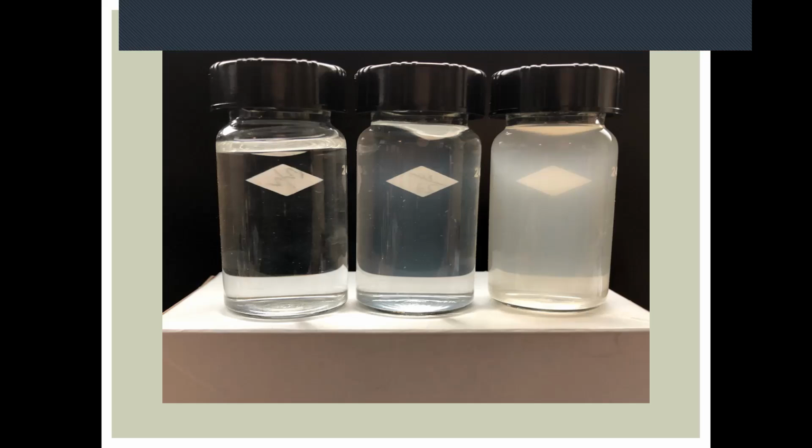So I assume other states have similar requirements, but I just want to note the 25 NTUs doesn't take much to achieve that. And pretty much any amount of eroded sediment will have enough fines in it to cause you to not meet that 25.